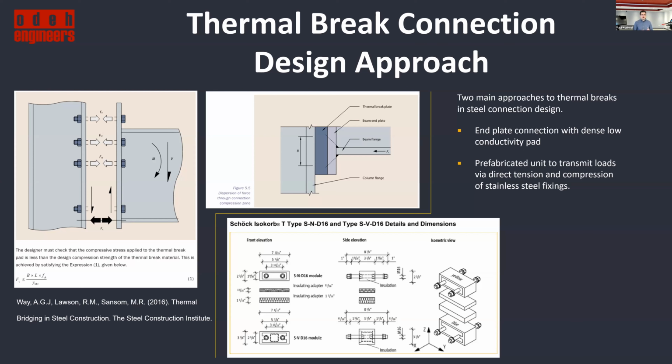It's kind of like a double nut between your plates. And in the bottom connection, you have a stainless steel sort of more or less pipe that's in direct bearing. Now, it's not to say that you couldn't use that bottom connection throughout your thermal break assembly, but in terms of these units, like I'm sure we've all seen, it's important to recognize that that's what's being provided.